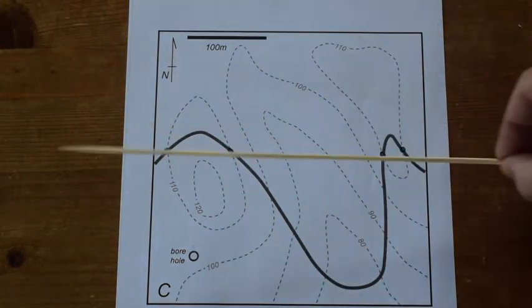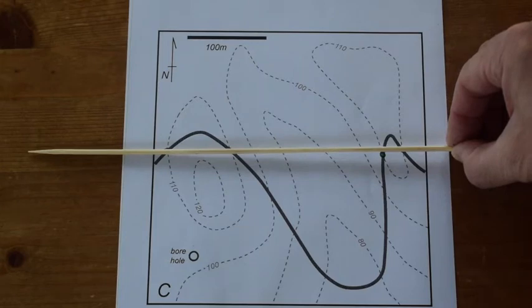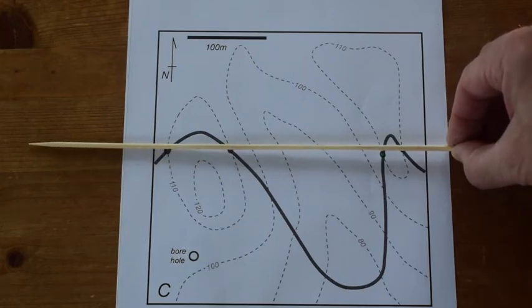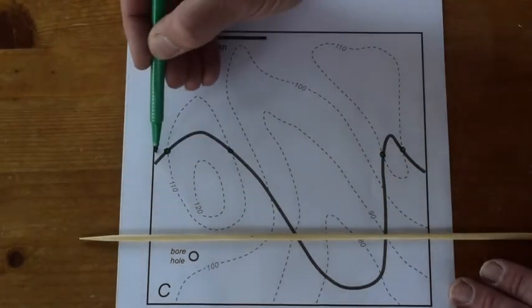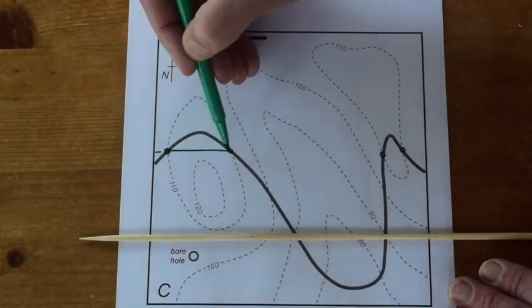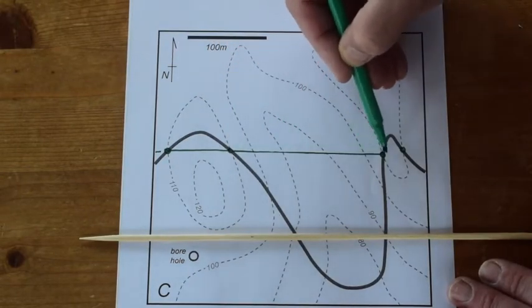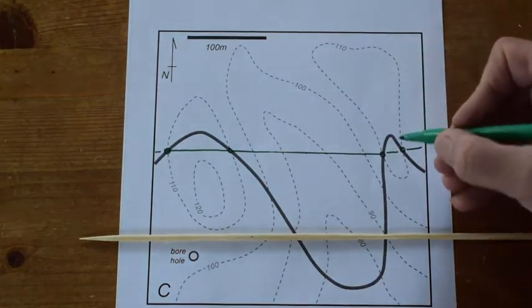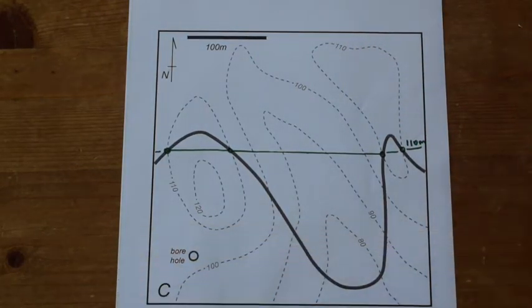Well, I can see that these all line up onto a near perfect straight line, which means that the boundary has a near constant strike for this area. And so we can join these up as a straight line. I'm nevertheless going to just freehand it in because I don't want to imply that it's necessarily perfectly straight. So this is the structure contour of value 110 metres. And it's worth labelling it up as you go.